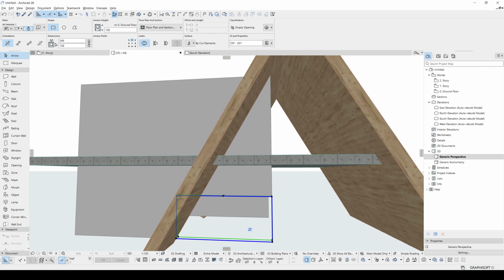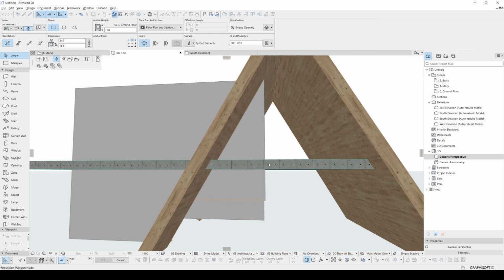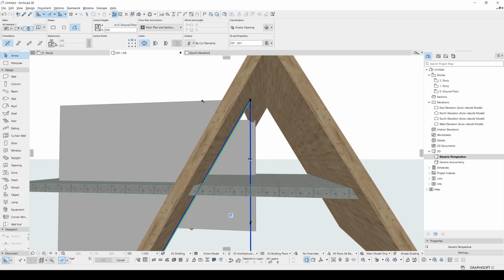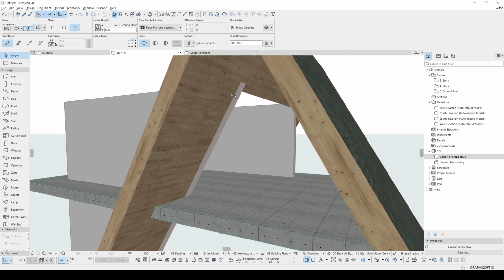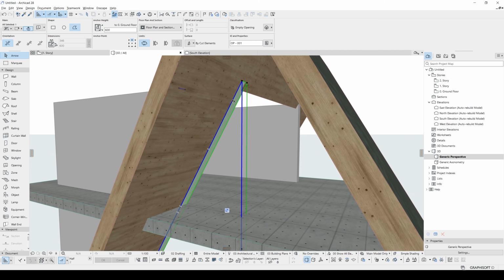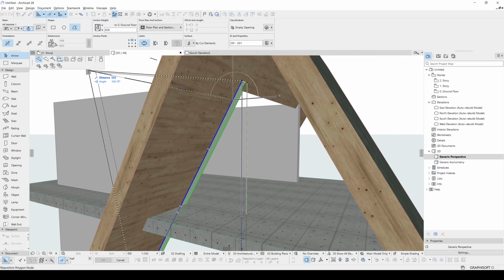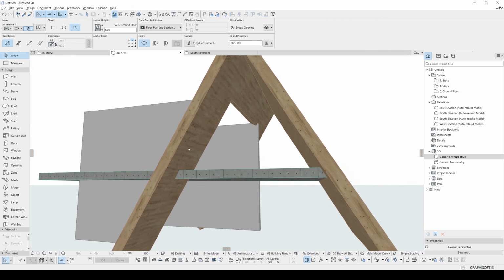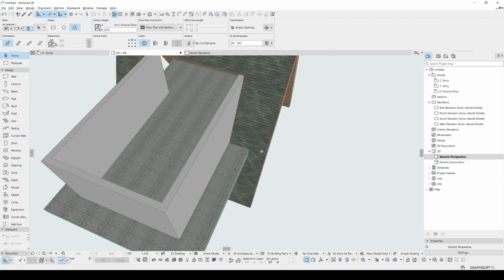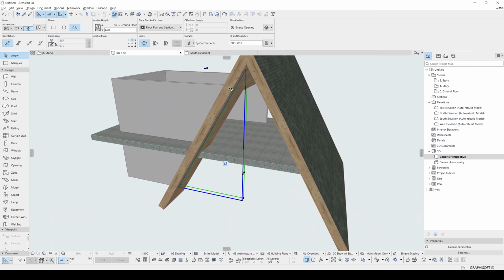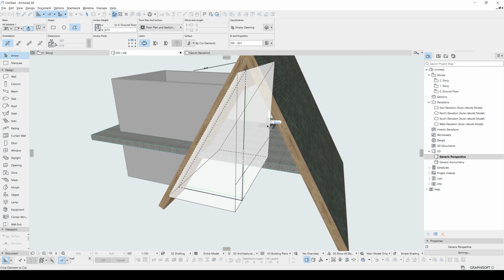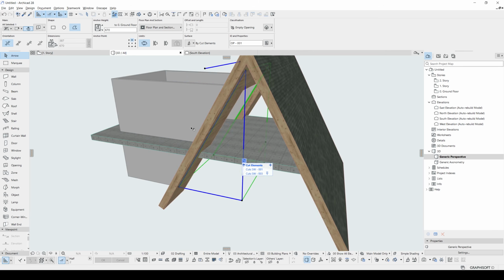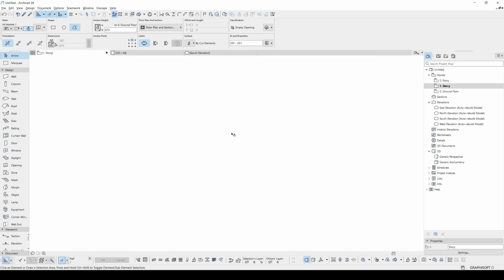And also you can change the location of the corners. If we look from this side, it's not looking well. To fix it, I will offset this edge to here. And it's way better. To cut out the second wall, we are just going to select this icon, hit this plus, and select the second wall. There we go.